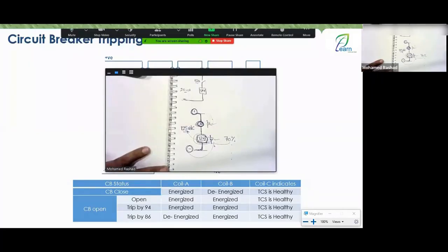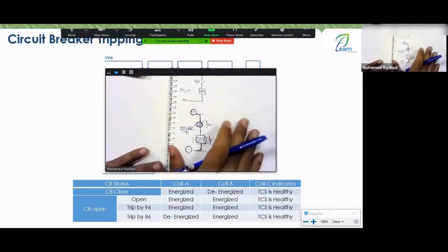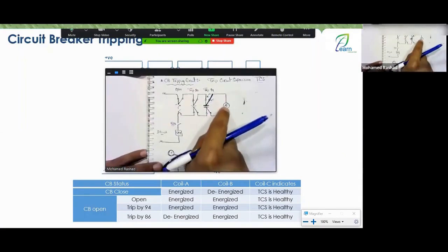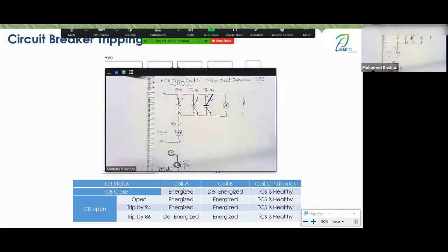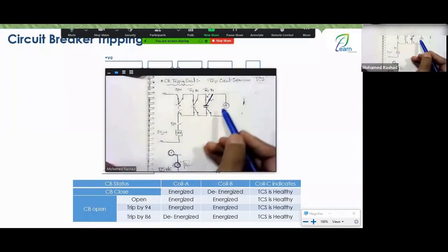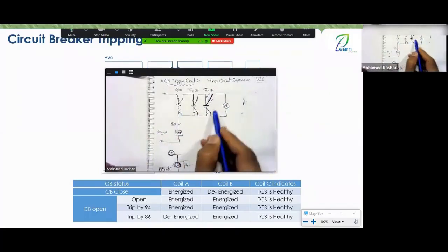That's good, okay. Engineer Rashad, suppose the voltage here is divided between these two. For example, this one takes 40 volts while the other takes 85 volts. In this case, the breaker will trip, right or wrong? I told you right, okay? And is this required? No, of course not. Why? Because this is used for monitoring, meaning its role is to monitor and not to cause a disturbance or deliver power to the trip coil under normal conditions to make the breaker trip. That's not its purpose, to send a trip signal.